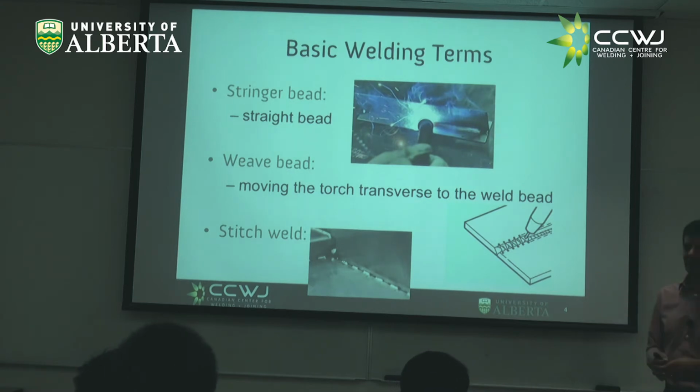Stringer bead means you weld straight, right? As if it was a string. Welders hate it because there is no room for fixing. What welders love, right, is weaving. And you see this kind of stitching process, this is just indicating the path of the torch.